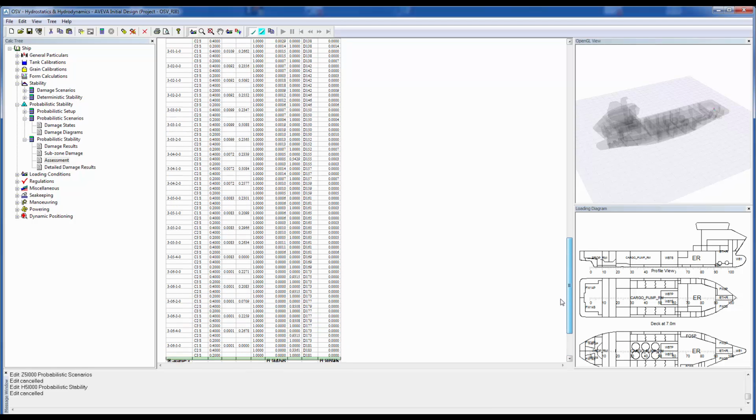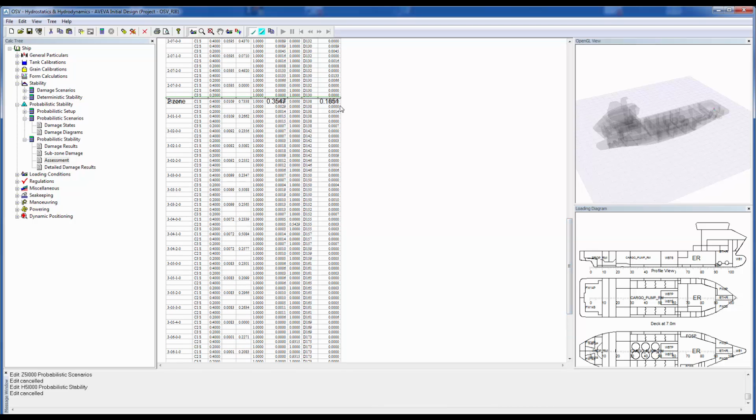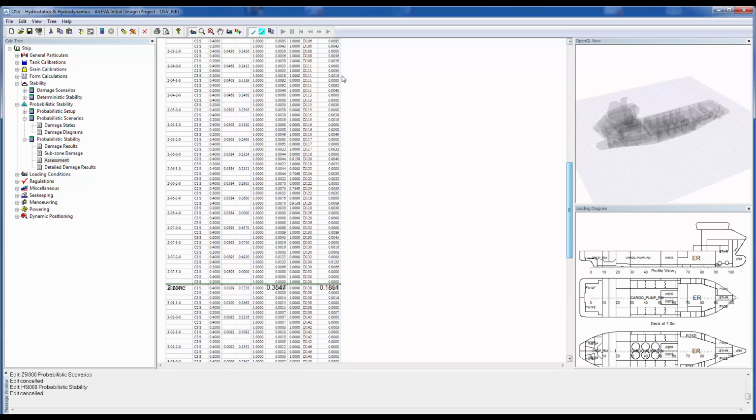So above this, our table shows how the attained index is being accumulated, and for each zone the selected damage case, its stability, its probability and its stability associated with it to give it its overall p-value, s-value. Let's see, the overall attained index for that particular case.